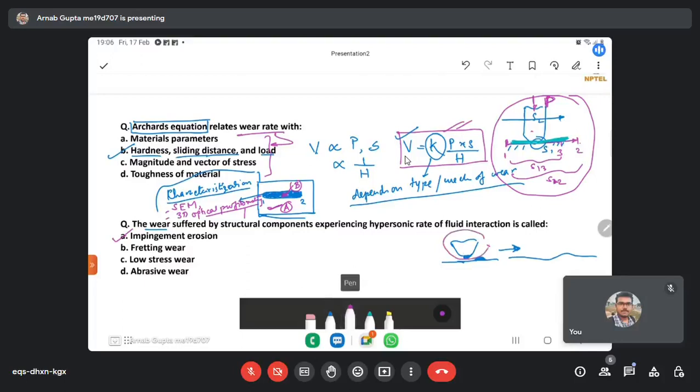Okay, so in that case, won't you say that the functionality of this component is also degraded? I mean, say foreign material, some particles are getting embedded on my surface, on this component surface or the surface that is concerned. So in that case also we will say that degradation is happening, right? So wear can be manifested in different forms, not only loss of material. It can be loss of shape, loss of functionality or performance, and yeah, more obviously the loss of material.